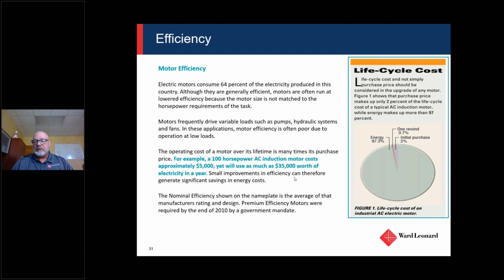If it's fully loaded, it is what it is, right? But if you have partial load, and we have an opportunity to turn the motor down from a frequency perspective, a speed perspective, or a load perspective and draw less current, then there's definitely a payback scenario there. That's really why we put this slide in here: efficiency is relational to the application, right? If you have something that needs 100% load 100% of the time, then it costs what it costs. But if it's a varying load, then we may be able to help you out and save you some money.